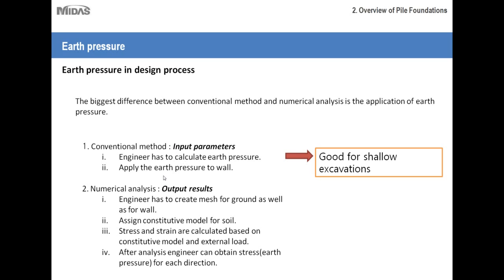As far as numerical analysis is concerned, your main focus will then be, instead of input parameters, on the output results. For numerical analysis, you have to have a certain skill set that applies to modeling. The engineer has to create mesh for the ground as well as the wall. So you have to understand how to use the particular program you're using to create these components. You need to understand how to create mesh sets for soils as well as structural components such as walls or bracings.